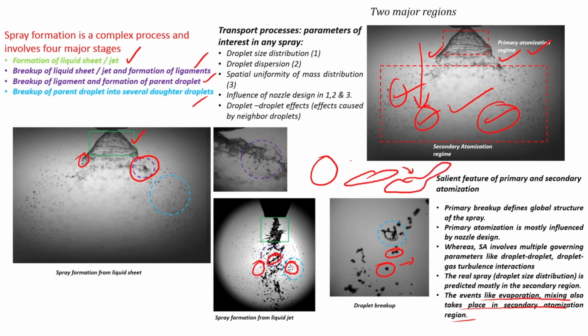Obviously, all these shapes are unstable, because a droplet or liquid blob always tries to be spherical no matter what. In that process it starts to split and generates smaller and smaller droplets. As it becomes very small, surface tension becomes very important, and those droplets become very stable. So when evaporation and mixing take place, the droplets can be considered spherical. All the analysis we did earlier on droplet evaporation holds, but not for very large droplets, because large droplets are unstable inherently, especially in a high speed flow.